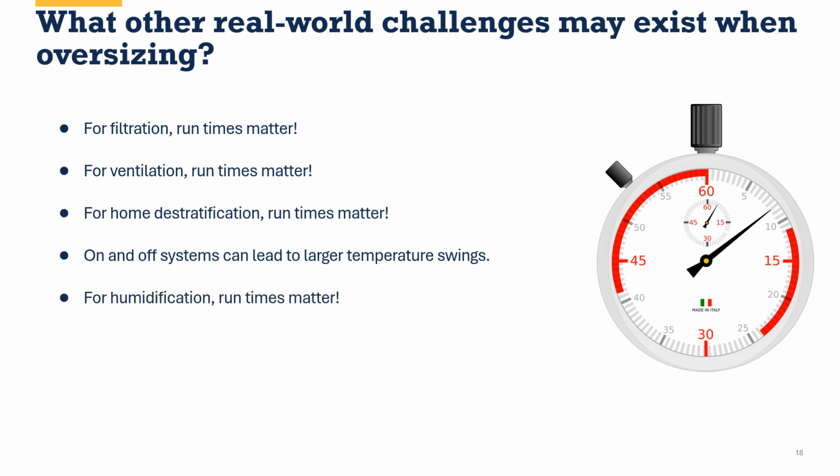If we're trying to, in Colorado, add humidity to our home, we could actually be using something like a steam humidifier that we connect to our central system, or maybe we have standalone humidifiers in parts of the house and we're relying on that central air handler to move that air around. Guess what? If you want that to have more even humidity distribution throughout the home, you need to have that long run time.